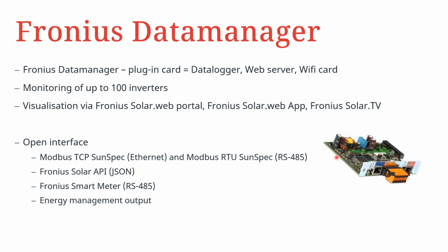Otherwise, the interaction between the data manager and the sensor card, if it's a sensor box that is used, as we are going to see later, the interaction is actually within the SolarNet ring. But if you have a data manager box instead of a data manager card, then you also have the interaction within the SolarNet ring. But if you have the card version of the data manager and the card version of the sensor, then you will have an interaction of the two through data communication onwards to SolarWeb for monitoring.